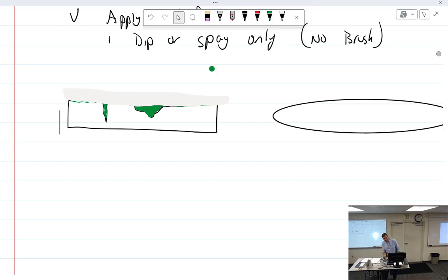I could imagine it like this, if you're doing crankcases all the time. Well, you just do a sample with a crankcase material, and if you did one section of it at, say, 15 seconds, and you were done, and it still got a green film like you did nothing, and then you did the next one, you waited 20 seconds, it was almost gone, but not quite, you went 25 seconds, that's to the base metal. So you then figured it out based upon that. I think they have it kind of figured out how much it should be for the most part. I don't think it's quite as trial and error as I make it sound.